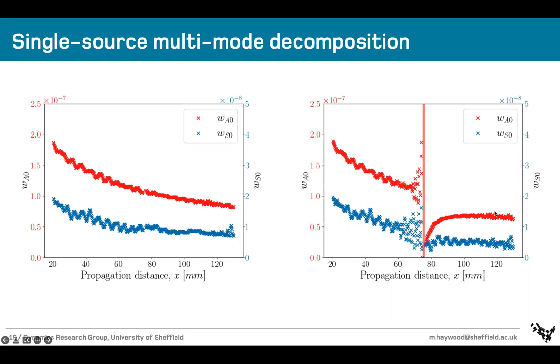significantly straight after damage. Without diving too much into the physics of it, damage causes a wave mode conversion from anti-symmetric to symmetric, or vice versa. This one is very clearly showing quite a strong conversion of this A0 mode, so it drops straight after the damage. What this essentially shows is that the weights that we get out of this are inherent parametric features that indicate the energy, and it matches the physics that we know. So that's really nice.